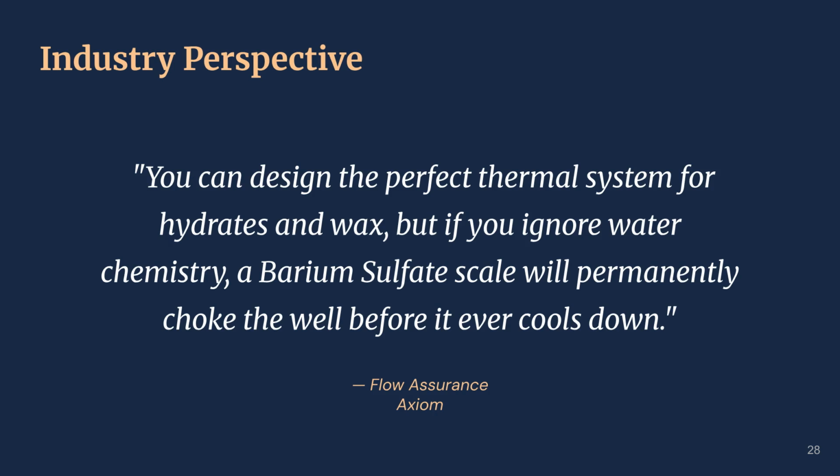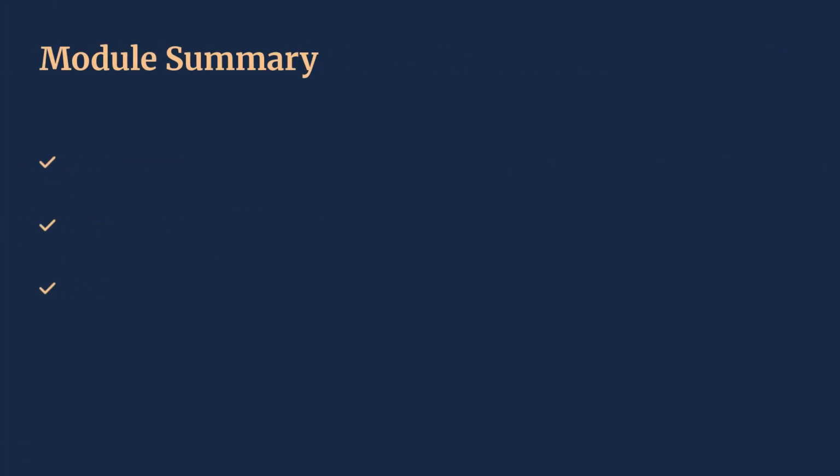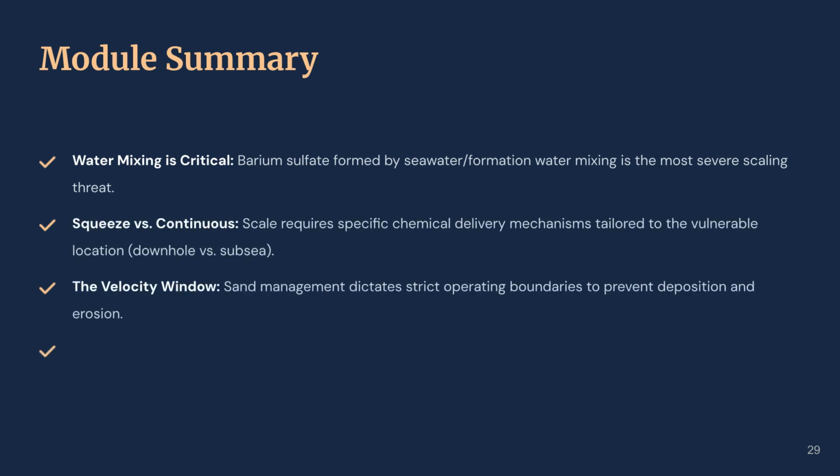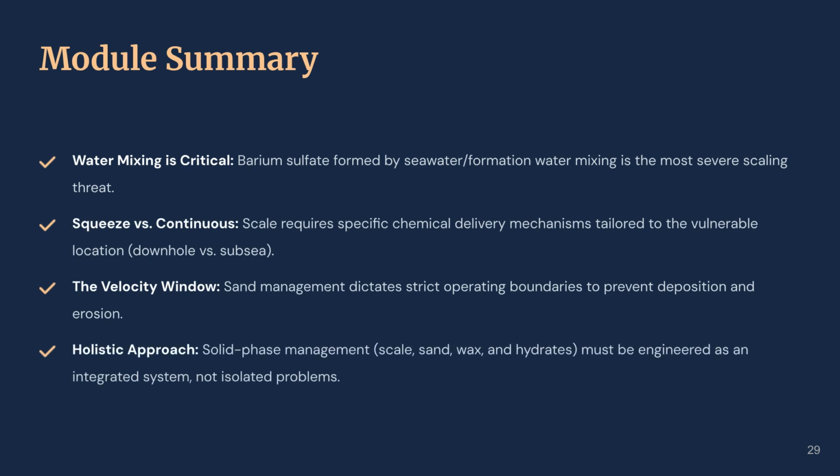A core flow assurance axiom reminds us that ignoring water chemistry can lead to permanent blockages from barium sulfate scale, effectively choking a well long before other thermal issues like wax or hydrates even develop. In summary, water mixing, targeted chemical delivery, and strict velocity windows are foundational to successful management. A holistic approach is essential, viewing all solid phase risks as an integrated system rather than isolated problems.